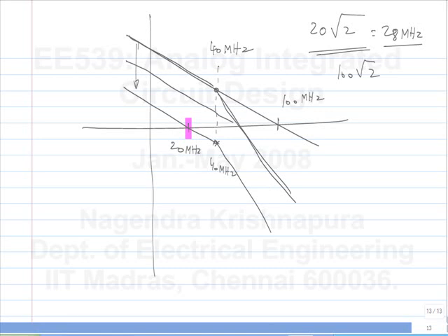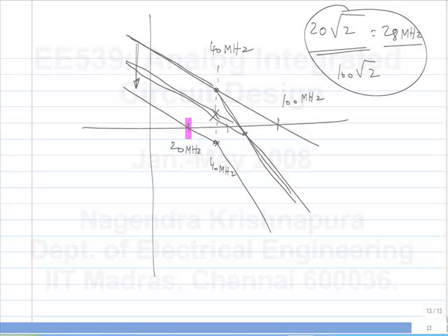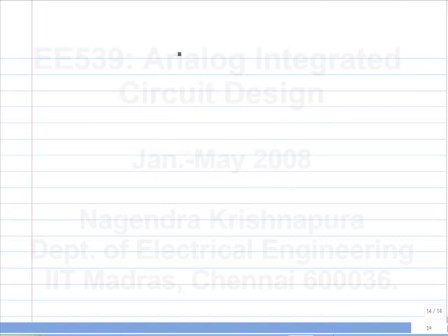So you don't have to reduce it by as much. So if you do something like this, the pole would have gone to a higher frequency and then it drops off. So both the loop gain reduces and the pole moves to higher frequencies. So the reduction in bandwidth is not as much as this. Okay. So we can work out what it is.